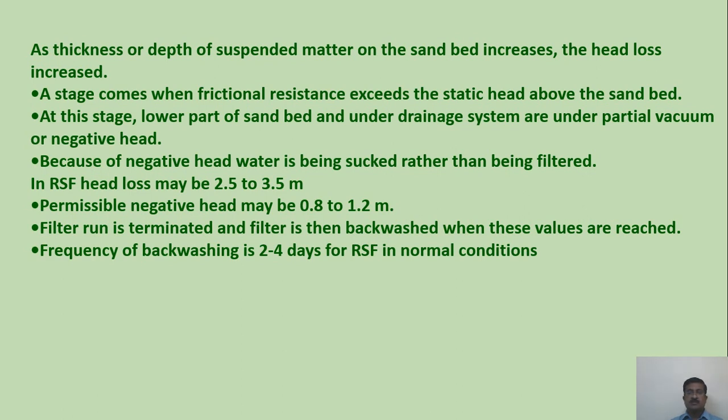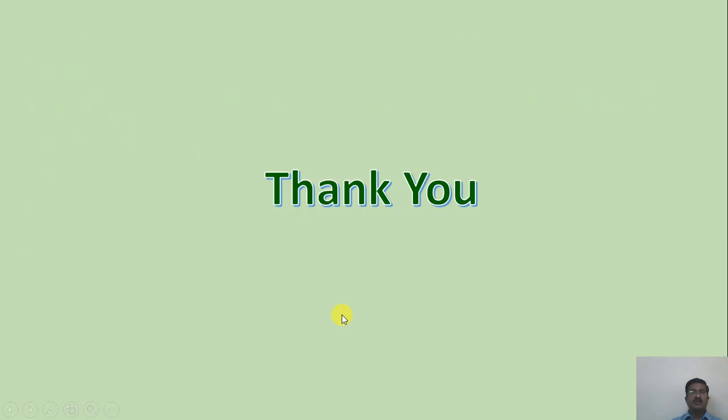This backwashing frequency depends upon what type of filter is used in the water treatment, and depending on the filtration rate, we will have to carry out the backwashing cycle. Today we have discussed all these points associated with the various types of filters. Not only that, we will also have to keep watch on all the filter operations to avoid filter troubles, and the backwashing cycle should be run properly. It is necessary to observe the filtration rate so that the head loss or negative head loss is monitored.